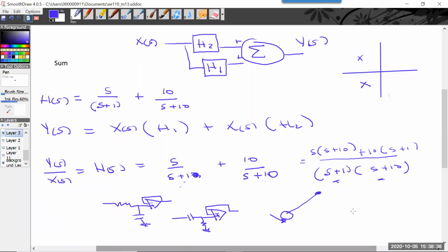So that's what allows you to get complex poles. If I have a mass and a spring and a damper, that spring is a different kind of energy storage element than mass. So that allows you to get complex poles.